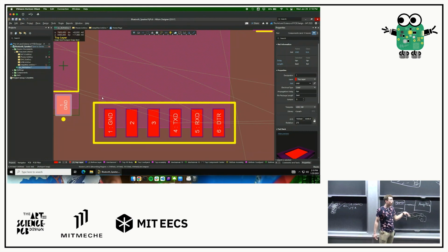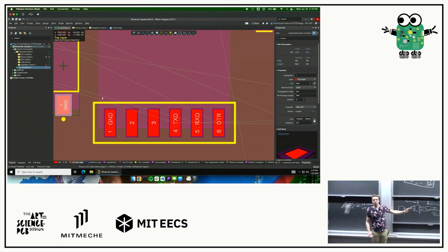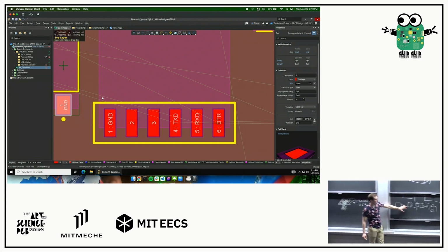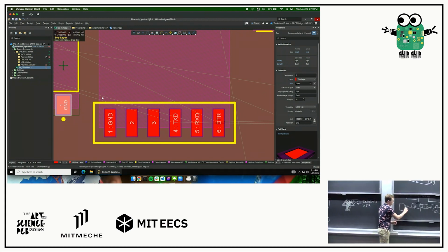A cause for making it a bit smaller is, let's say you have a chip that has some really tight pin spacing, and each one of these guys is only 8 mil tall, something like this. If we try and put a 10 mil trace in there, we'll get something that kind of looks like this, right?